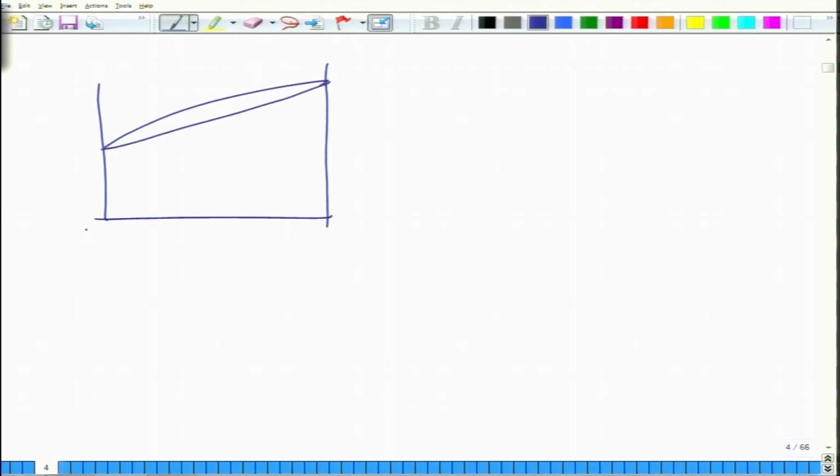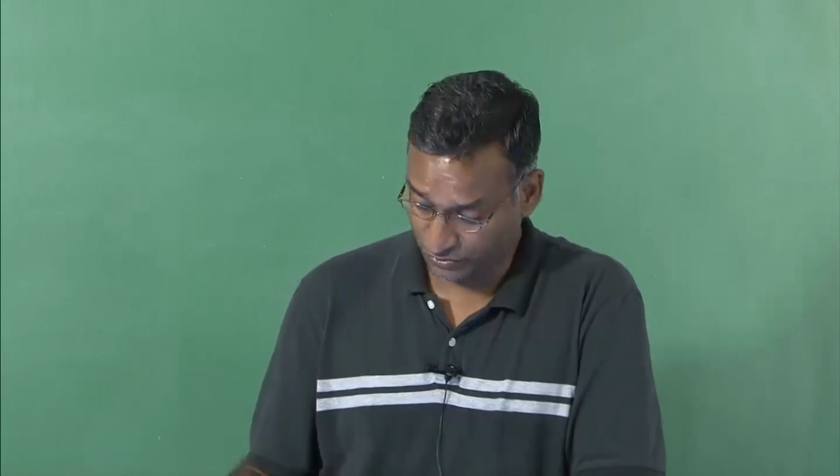So, this is a binary system, let us say AB. As you decrease the temperature for a given alloy, the tie lines vary like this, okay, as you go from the start to the end of the solidification. So, this is composition C naught. Tie lines in a binary system are flat and parallel to each other, whereas in a ternary phase diagram, the tie lines need not be parallel to each other.